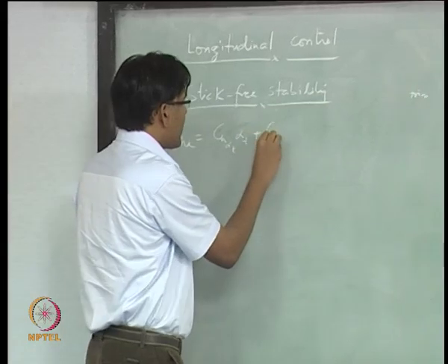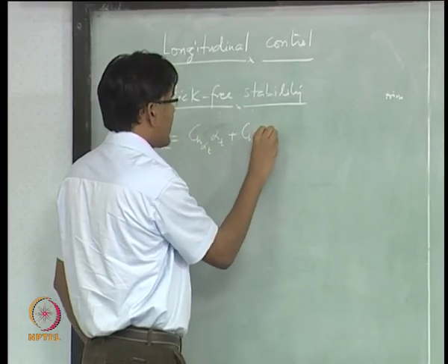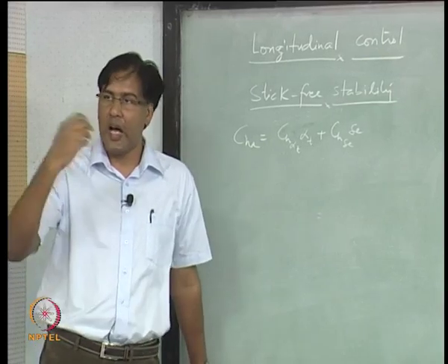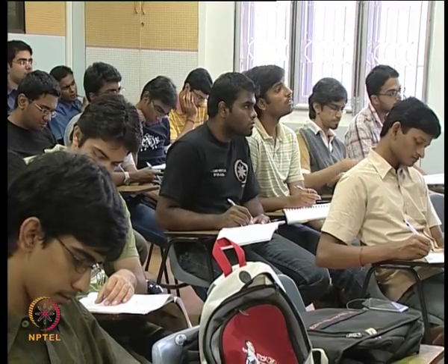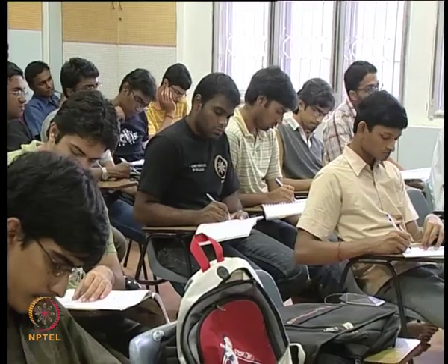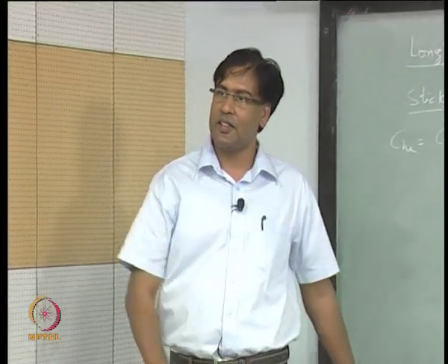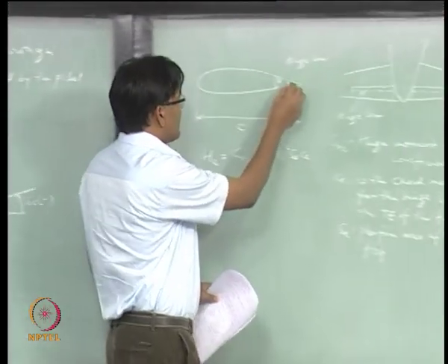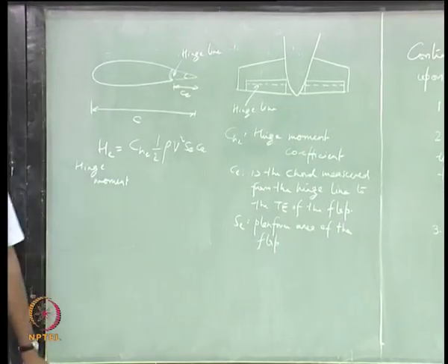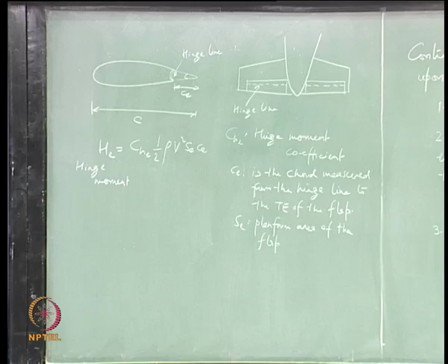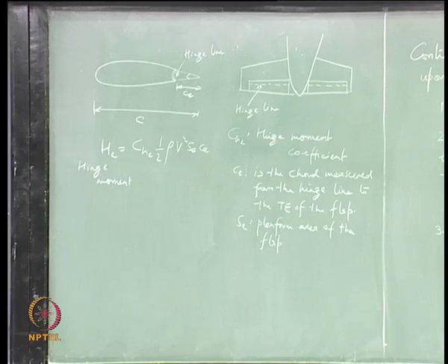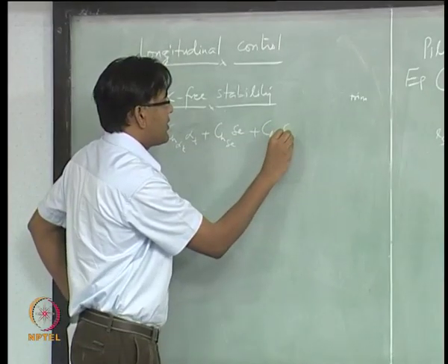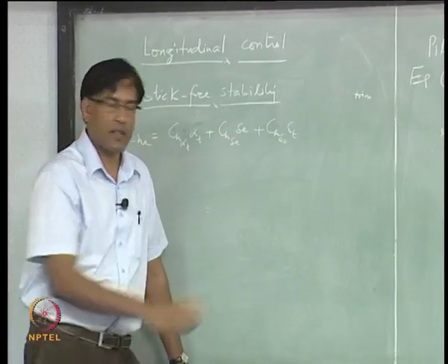So it is also going to depend upon the elevator deflection, right. If you have a tab, which we will talk about later, okay. If you have a tab, which is a surface attached to the elevator, we will talk about this a little later. So it is also going to be a function of the tab deflection, okay.